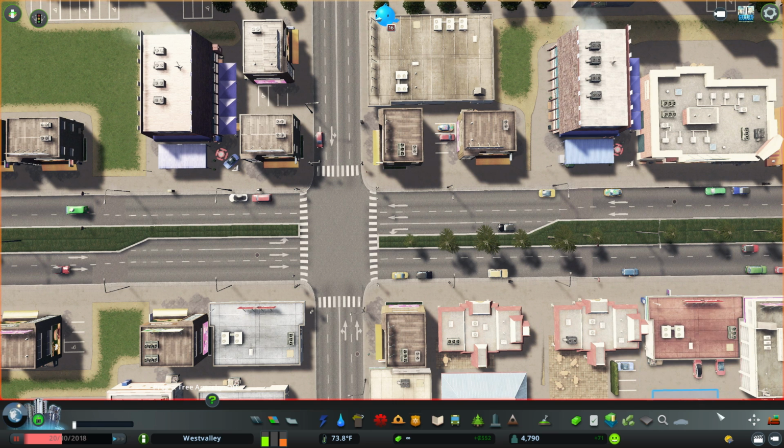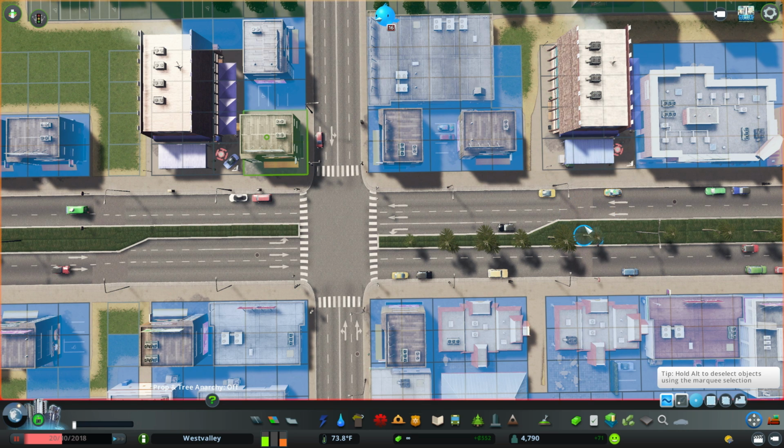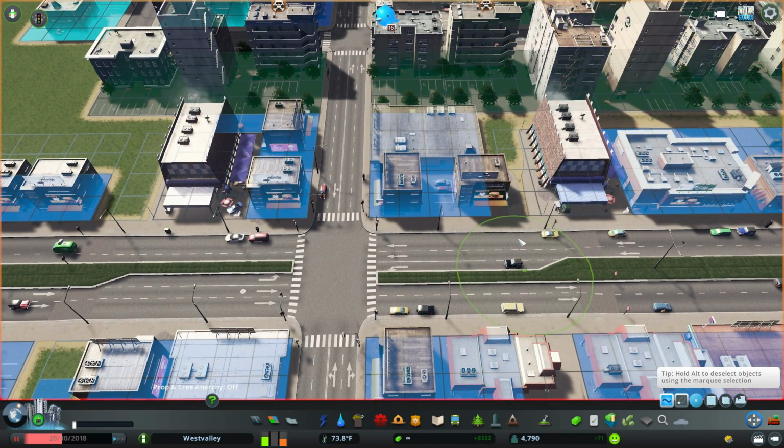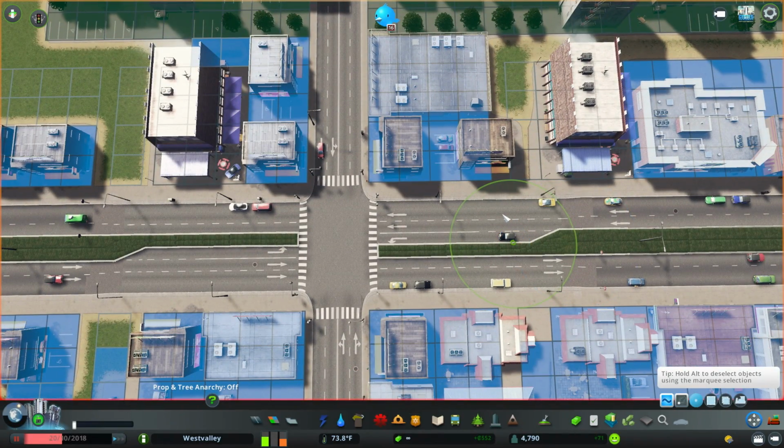One extra thing, if your traffic continues to clip the siding here, what you have to do is adjust the no point distance. So I find where my no points are, this one and this one, so I just move this a little bit to the side here. Like that.